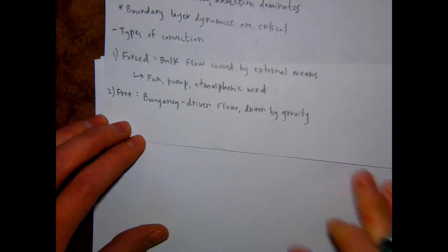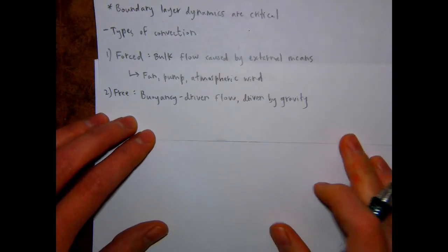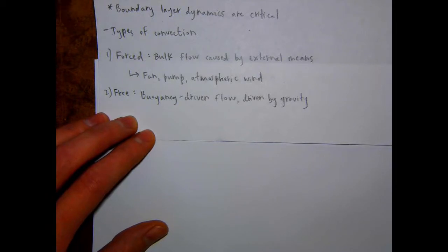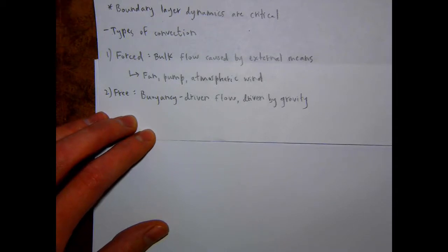And if you think about, say, you have an object that has free convection occurring, so you've got the flow moving this way, upward, due to gravity, and then you have a fan forcing air onto it in the downward direction. So in that case, the free and the forced convection would be operating kind of opposed to each other. You can also have them aligned. You can have the forced flow moving the same direction as the free flow, or perpendicular. So all three directions.